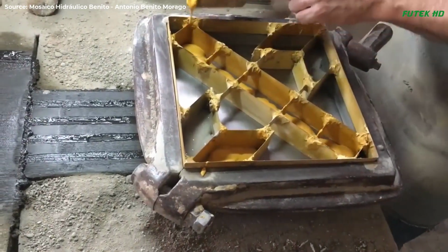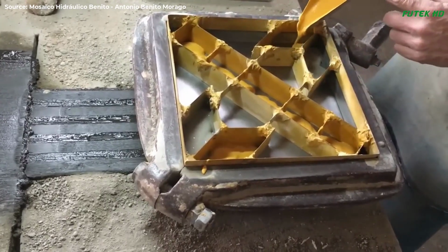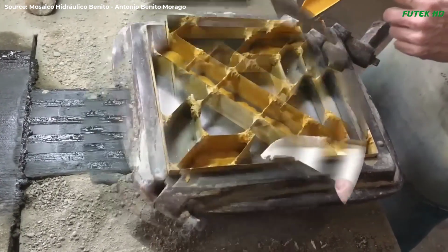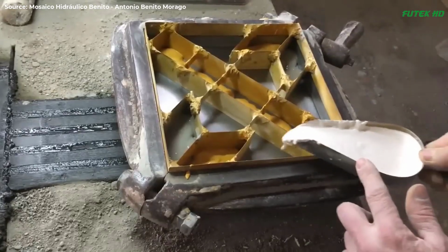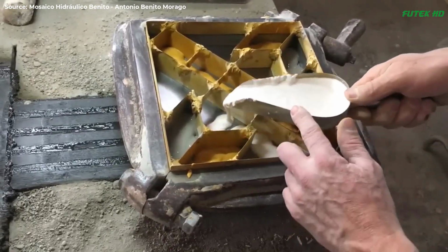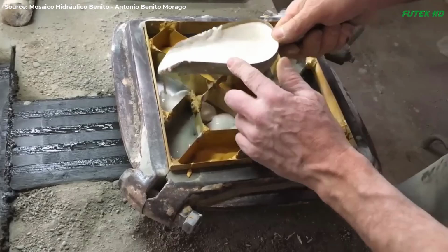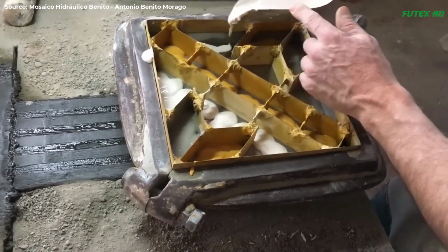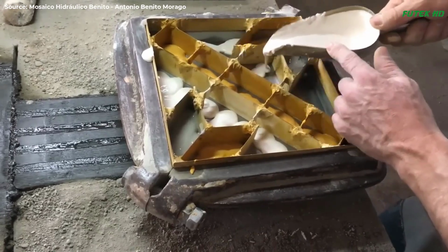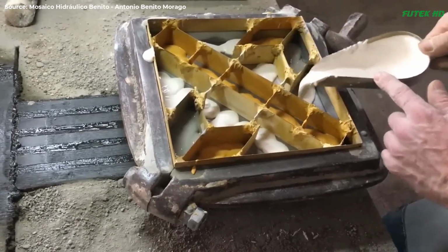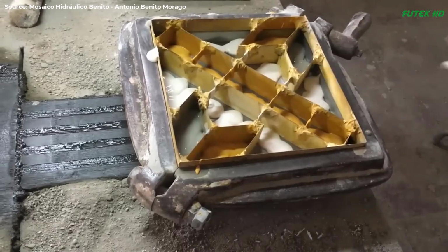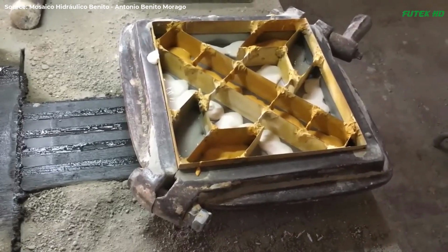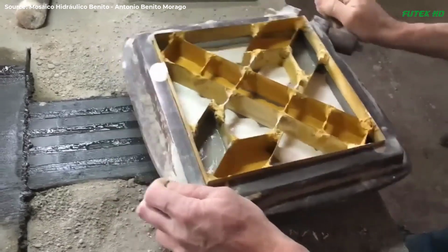The manufacturing process begins with the preparation of a high-quality cement mixture. This mixture includes high-resistance cement, marble powder, and siliceous aggregates, which provide the tiles with their durability and strength. Natural pigments are then added to this mixture to achieve the desired colors and patterns. These pigments are chosen for their quality and longevity, ensuring that the tiles maintain their vibrant appearance over time.